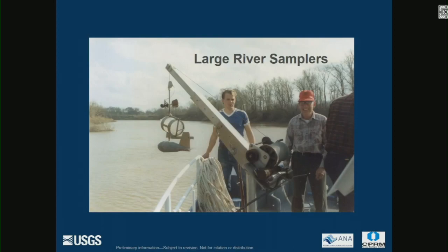We've seen some of these that Tim and Molly have shown in their presentation. You've heard from them. This is a frame sampler that the USGS used before we had the actual molded, nice looking, enclosed collapsible bag samplers like the D96 or the D99. Same type of setup with your MS8 sampler: a weight, hanger bar, frame. This just does not have the shield. And so it's an open frame.